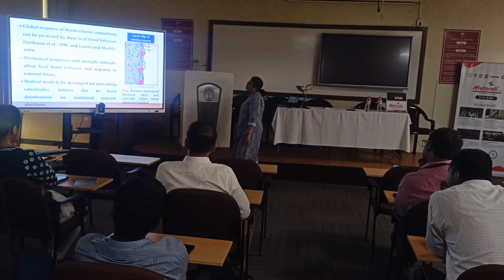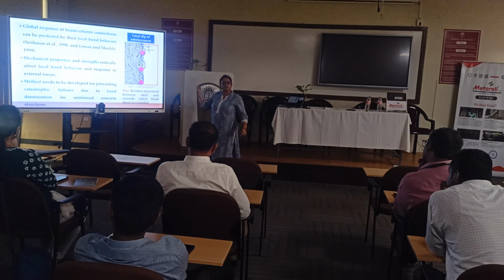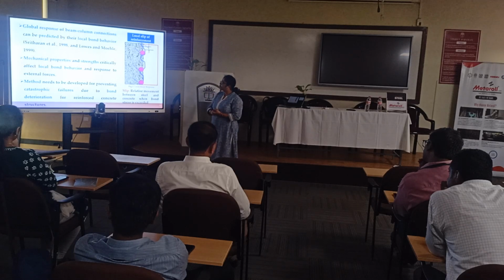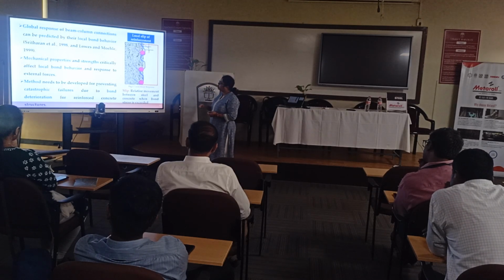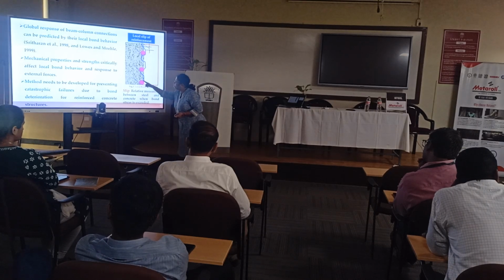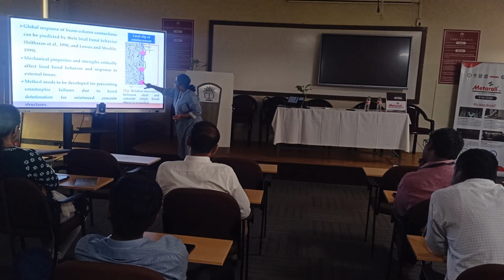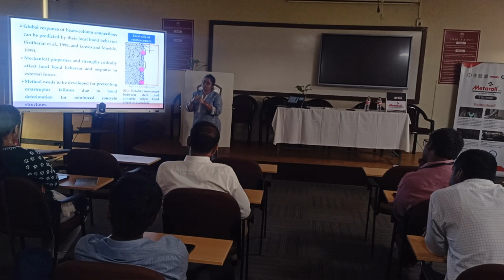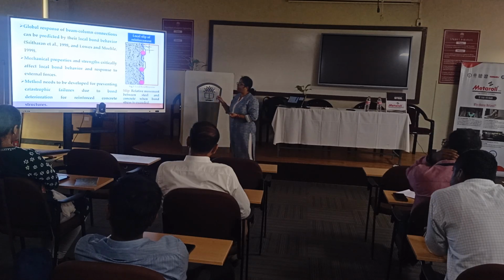Now, when you have the anchorage behavior and the bond fails due to the tensile pull, how does the crack appear? The maximum cracking will appear near the concrete surrounding the steel bar. These are the steel bars. Now, the concrete surrounding the steel bar gets crushed first. It depends on the grade of concrete, the grade of steel, and how much force you apply.